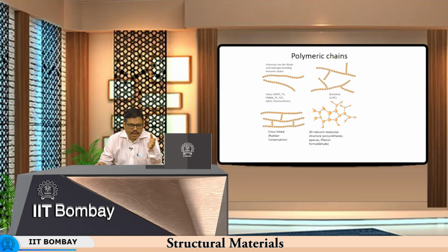In metals, the elastic strains recoverable are to the tune of 0.2%, which is an extremely small amount, and it is irrespective of how much deformation you have. For an undeformed material, it is 0.2%, and for deformed material, of course, it will depend upon the stress from which the unloading has taken place.